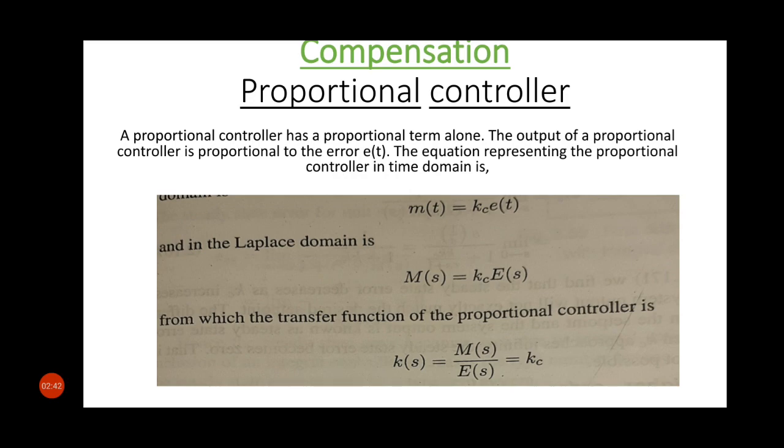But it is not possible to increase the steady state gain beyond a certain value. This steady state gain is sometimes called the proportional controller gain. For a system above second order, an increase in the gain drives the system towards instability.